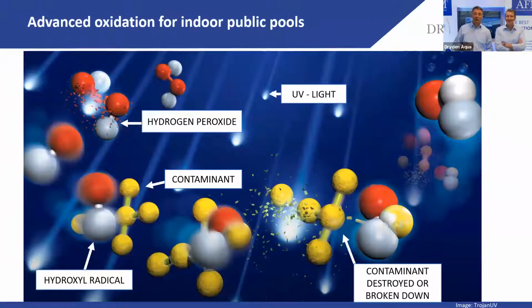Okay, good. Let's go to the Star Wars slide here. Yes, this is advanced oxidation. Advanced oxidation is oxidation with hydroxyl radicals. And the best way, and there are different ways, the sun itself, but small amounts. If you want to produce a massive amount of free radicals, the way to do it is that you split hydrogen peroxide, H2O2. How do you do this? Most effective with a very, very high dose of UV. These photons here, these Star Wars things, jump in.